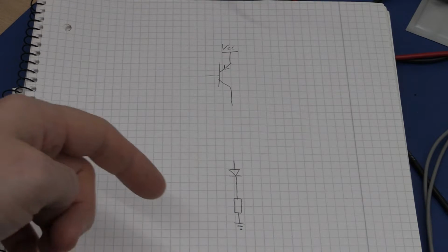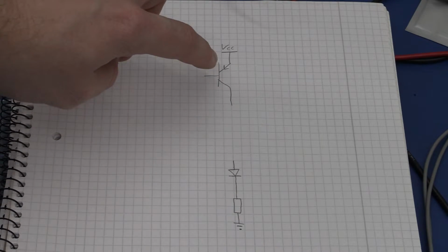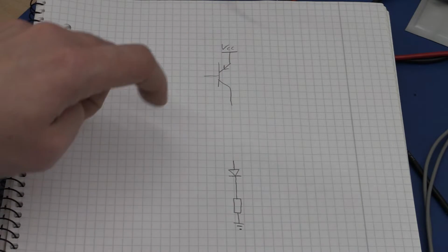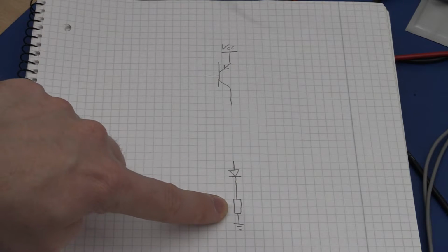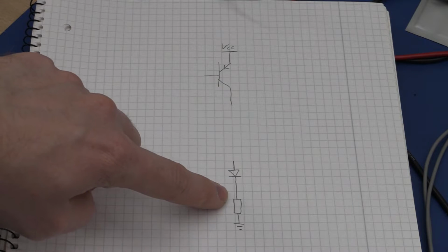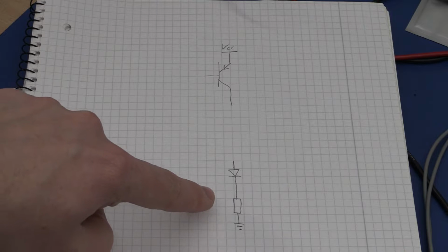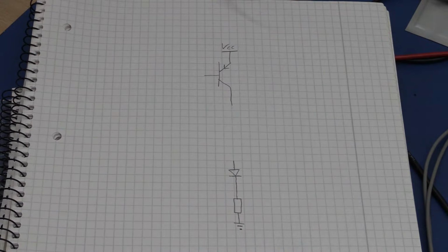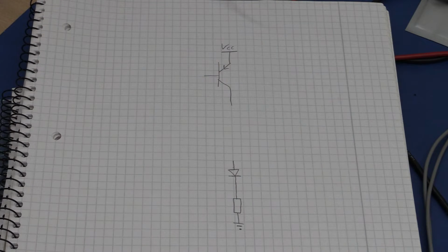So we will reuse some of the previous circuit from the video about the linear regulator. We still need a transistor to limit the current, else we will just burn out the LED, and we will need a resistor to measure the voltage across, similar to what we did. I chose to do it on the low side. I think that is the easiest when you're dealing with op amps and so on. But there's still no reason you couldn't do it on the high side if you desire.